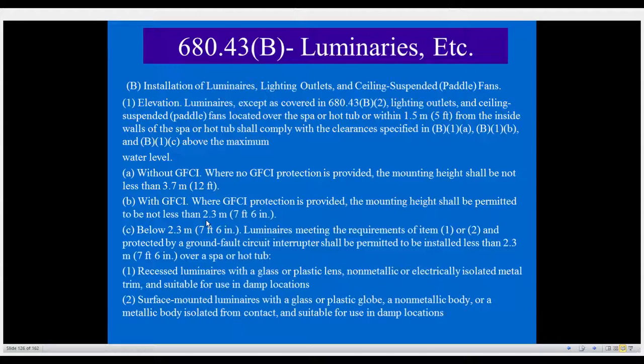Okay, so you do need to follow the instructions for these ceiling suspended paddle fans, and in many cases, wherever you install them, they have to be listed for that location. For example, if you did an outside application, like you would in part 2. So keeping that all in mind, you've got some information that you have to follow, and a lot of times it's going to give you a height that you have to maintain with this ceiling fan. So make sure you follow all of that information, and it's obviously within the purview of the inspector to ask you for the instructions for that ceiling fan if they think you mounted it too low.